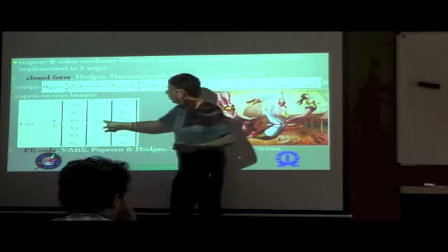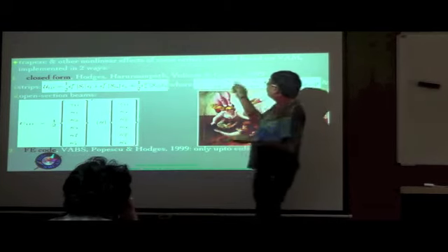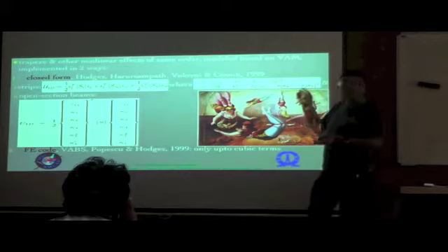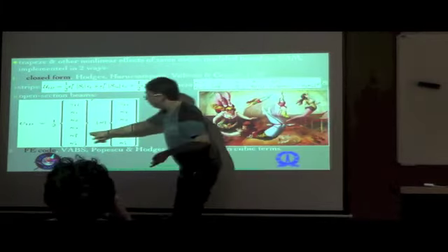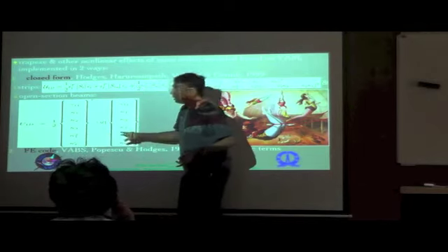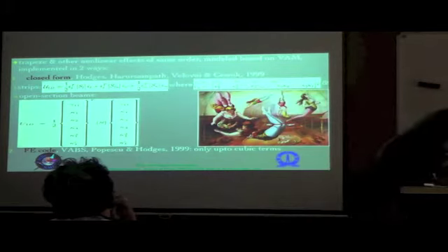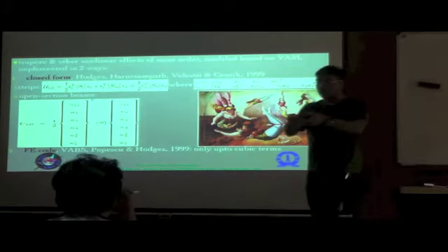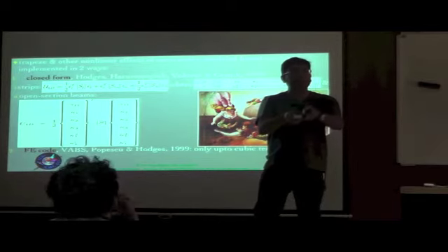In such a situation, you will end up with a matrix like this, much simpler if you compare to this as far as nonlinearities are concerned, because there are a whole lot more nonlinear terms here compared to here, where the only nonlinear term that you see is kappa 1 squared. It's very easy to see. You just take this strip, or probably just take two strips like this, and let's say we combine these strips like this to form an angle section, for example.